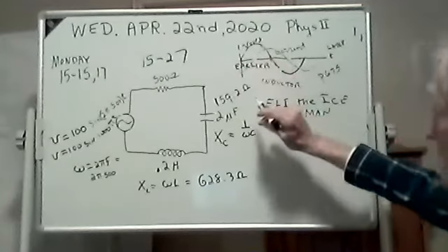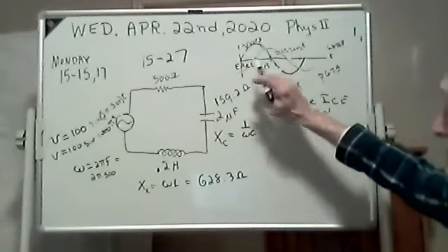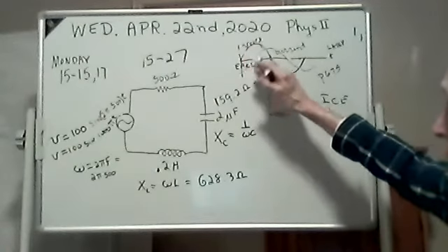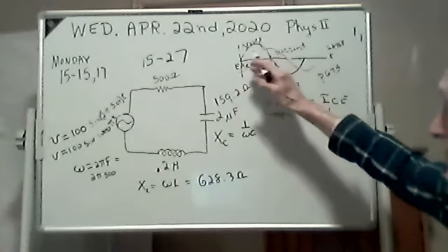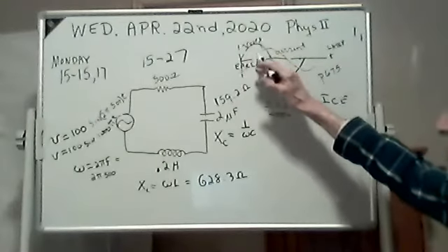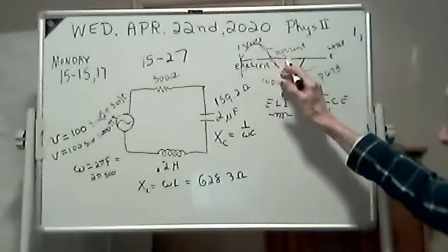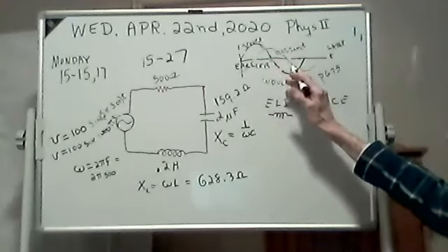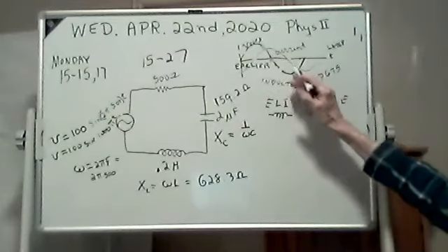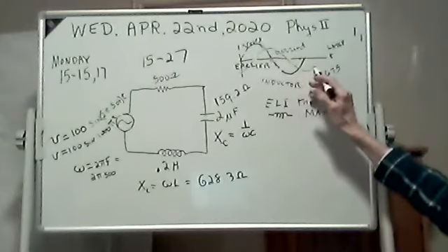Can you see that the volts peaks out before the current peaks out? The volts goes down through this axis before the current. The current goes through the axis here later, the time axis. The voltage bottoms out here. The current doesn't bottom out till later.